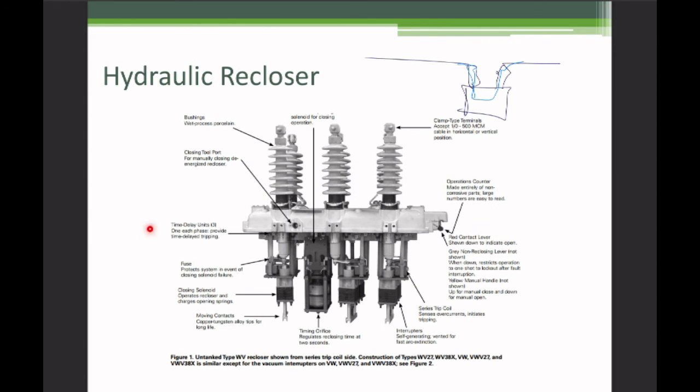If you want to change the time delay, right? So if this trips 3 times, that's going to require a certain set of parts here. If you want it to trip twice, the way you change that isn't programming. You pull it out of the oil, you unbolt the part right here, and you bolt a new one on for each phase with different mechanical properties, and that'll allow you to change your behaviors. So not programmable, but a very clever piece of engineering.